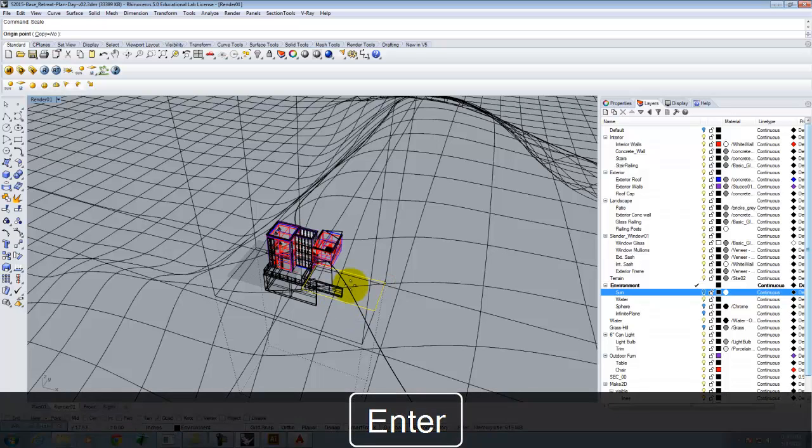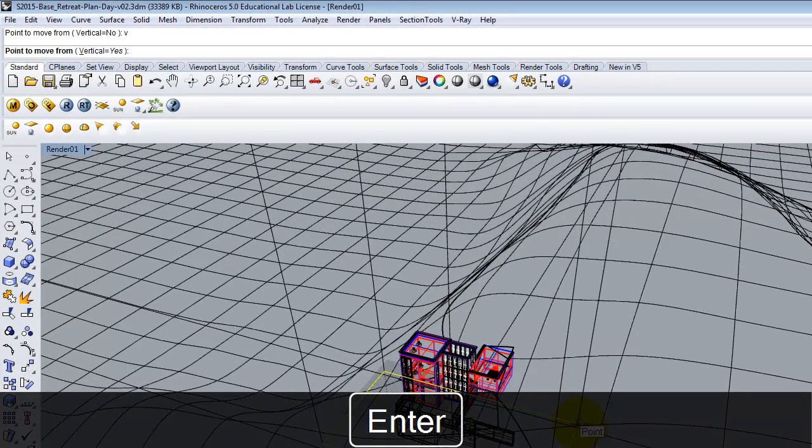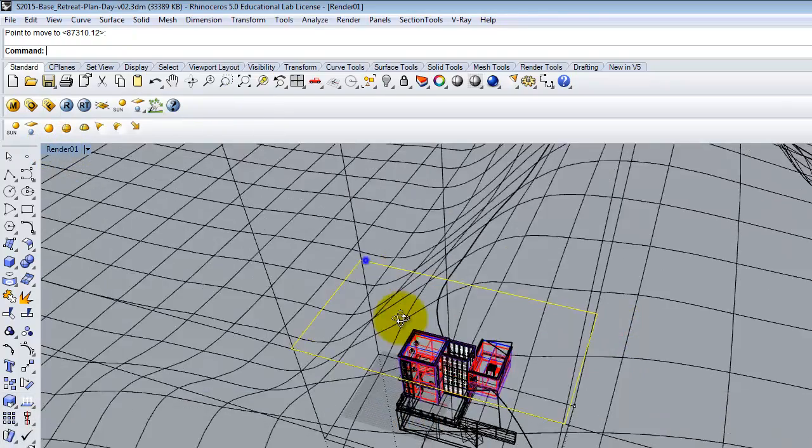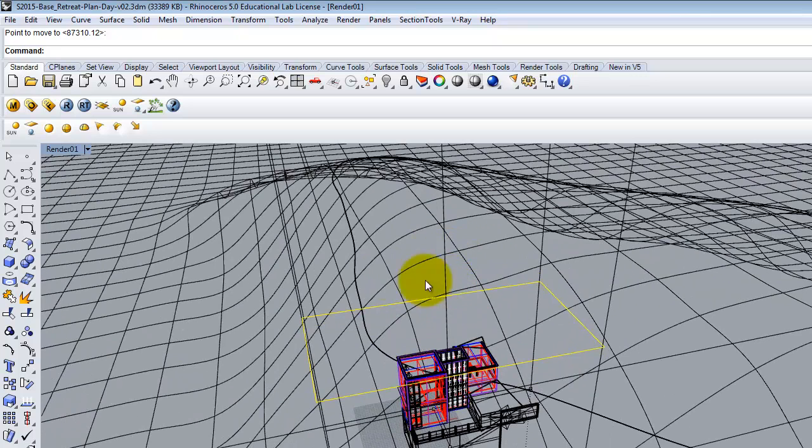So if I scale by 2, oops, I need a point here. It'll be the full size of my rectangle. Right? So let me go ahead and move it vertically so it's above everything else. About like that. This is my view. This is what I'm looking at. So if I have that active when I do the Make 2D, it's going to give me the actual border, which makes dropping the images in really, really easy. Okay? So let's go back to that front view here.